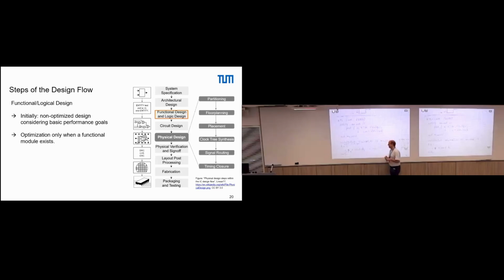The difference, in other words, is that if you operate on variables, they would behave like that. But if you operate on signals, like here, you have this kind of assignment operator, and it does not matter what the order is. So all of these lines are virtually processed in parallel. Of course, if you do the simulation on a computer, it has to do something sequential. We talk about the simulation stuff later. But virtually, from how you think about this, all of this happens fully in parallel.